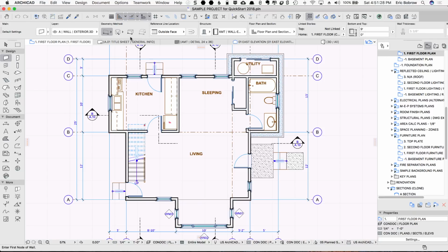Now, to draw a wall, for example, if I go here and switch to the polywall method, I click on one point, move this around, you can see the little preview. I can snap it to the axis. You can see the y-axis is indicated, and I can have a distance, and I might type in that I want this to be 8 feet or 2.5 meters, whatever you want, and then hit enter or return on the keyboard. That completes that action.